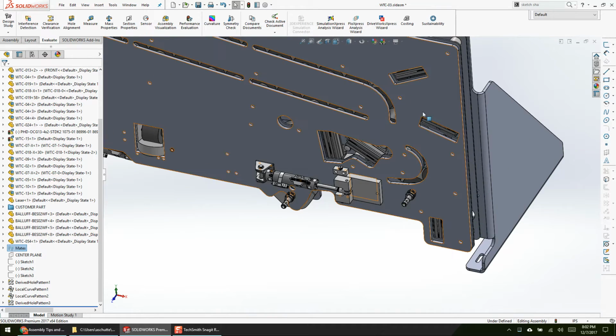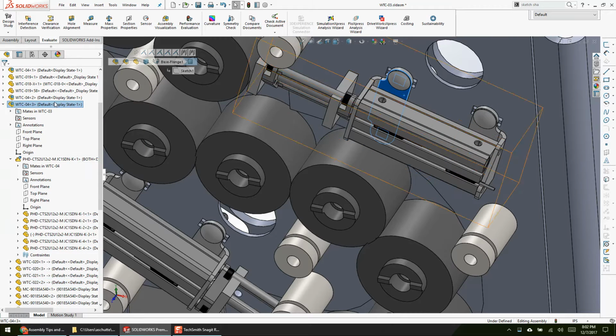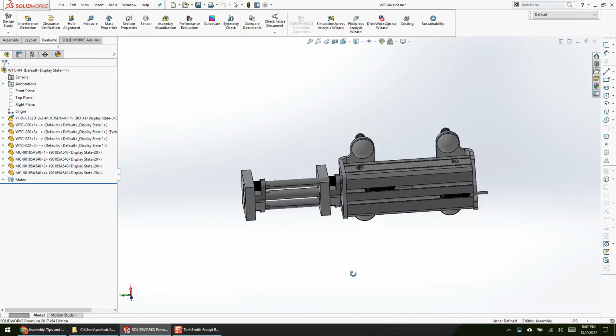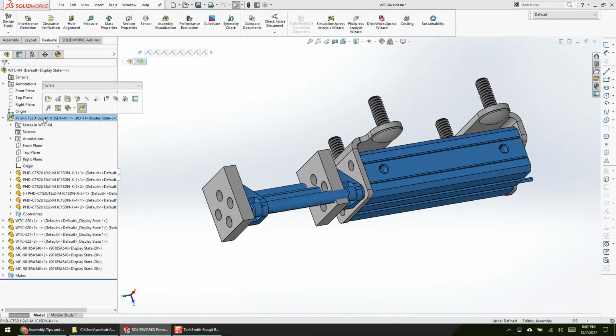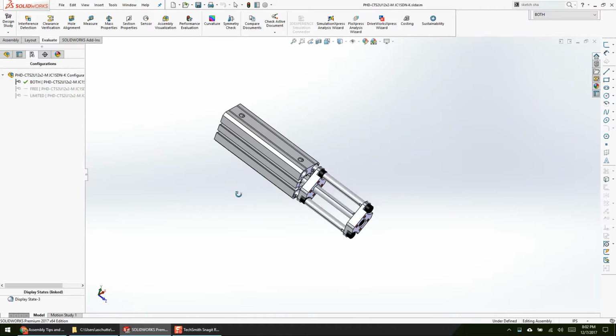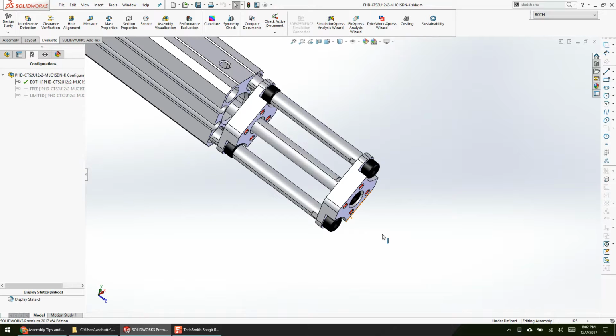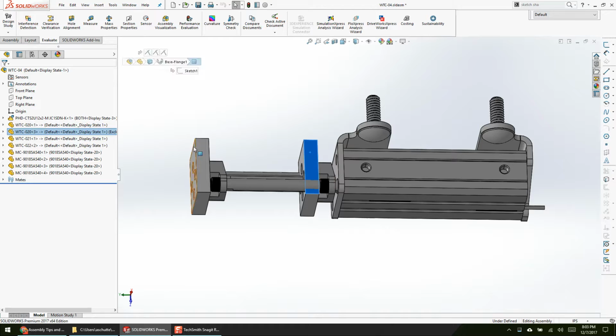Yeah, so clearly, we'll use this example here. So clearly this is a subassembly, right? Because I use this like 4 times in the design. And I've just duplicated, you can show kinematic motion, or you can just duplicate the objects. So in this particular instance, I said, here's where it is extended and here's where it is retracted, because I didn't have to show the kinematic motion. And showing the kinematic motion is more work, or configuring it and flipping through them. So I just have constant design feedback. So I just have 2 of these in my design, and one of them is excluded from bill of material. So I visually see 2 objects in my design.